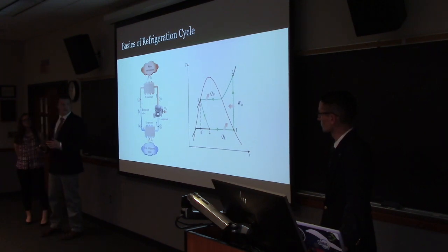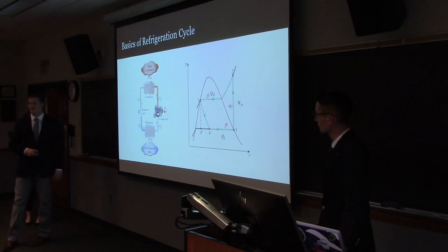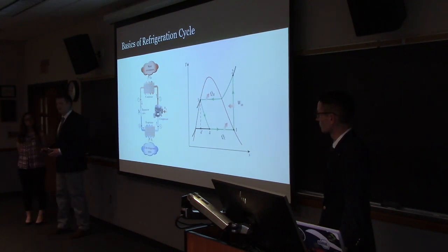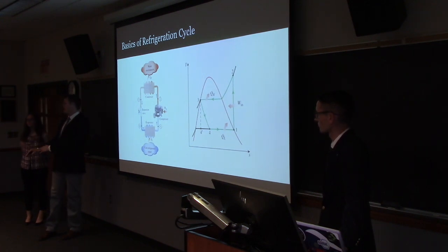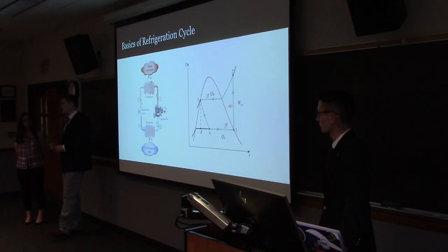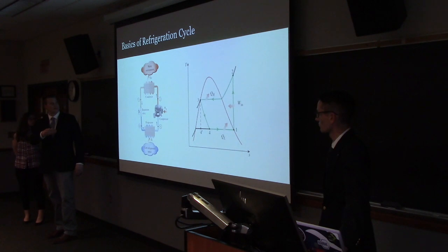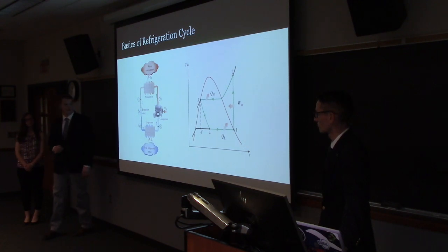Basically, the compressor will move the refrigerant through the entire system, and the condenser and the evaporator essentially move heat throughout the system. An evaporator will take heat out of the system, and the condenser will push heat into a heat sink. For example, in a refrigerator, the cold refrigerated space is the evaporator, kind of like the inside of the refrigerator, and then the refrigerant will go through the cycle. It will pick up heat from inside the refrigerator, and it will displace it outside of the refrigerator. It'll keep the inside of your refrigerator cool while displacing the hot air outside.